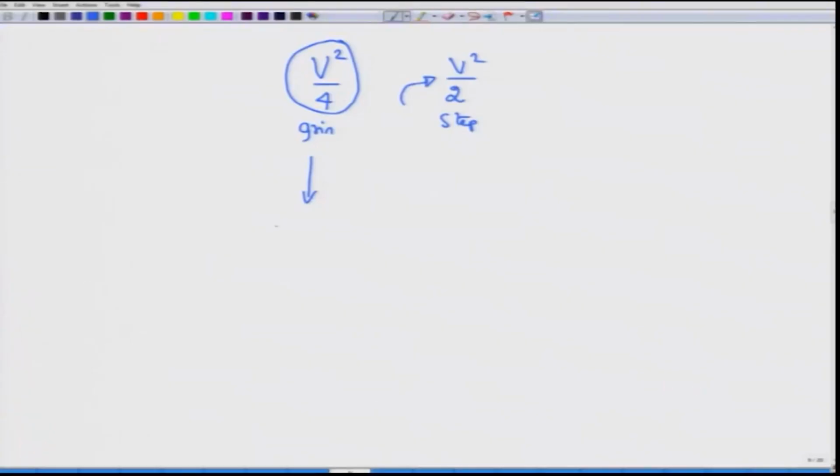In fact, I will not solve the equations, but I will give you an expression for the modal delay because of this graded index profile, and only for the case where alpha equals 2. It turns out that this is given by n1, where n1 is the maximum value of the core at the center, times delta square by 2, whereas the same value for step index fiber is n1 delta by c.